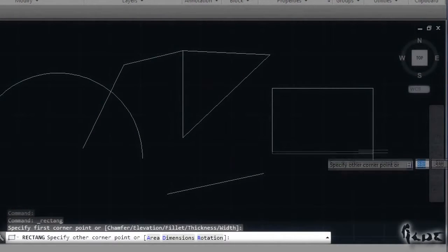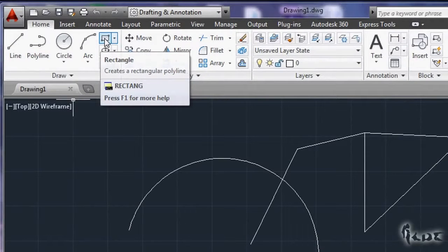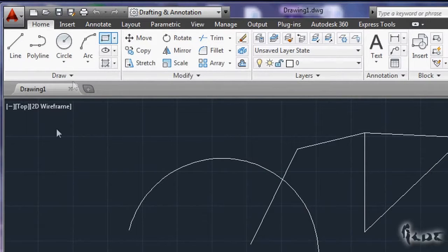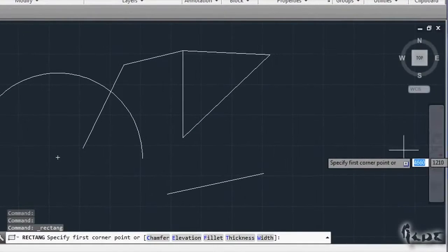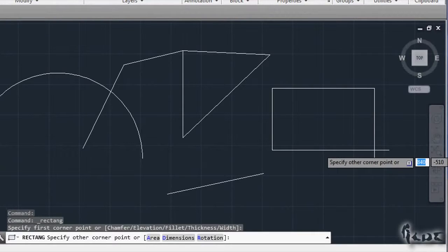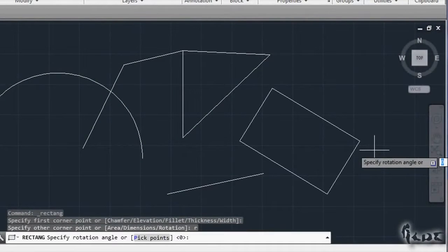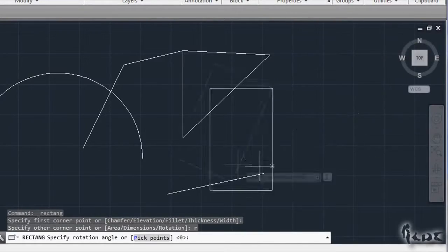Each time you draw or do anything, the command line will tell you what to do or any choices, which are indicated through brackets. Choose rectangle. After you set the first point, you can put a precise area or rotation. If you want to rotate your shape, just type R in the white slot next to your pointer. This is used to type a command. If the command Rotation has the blue letter R below, it means that you need to type R in such white slot to run it. Press then the Enter key to enter the command.